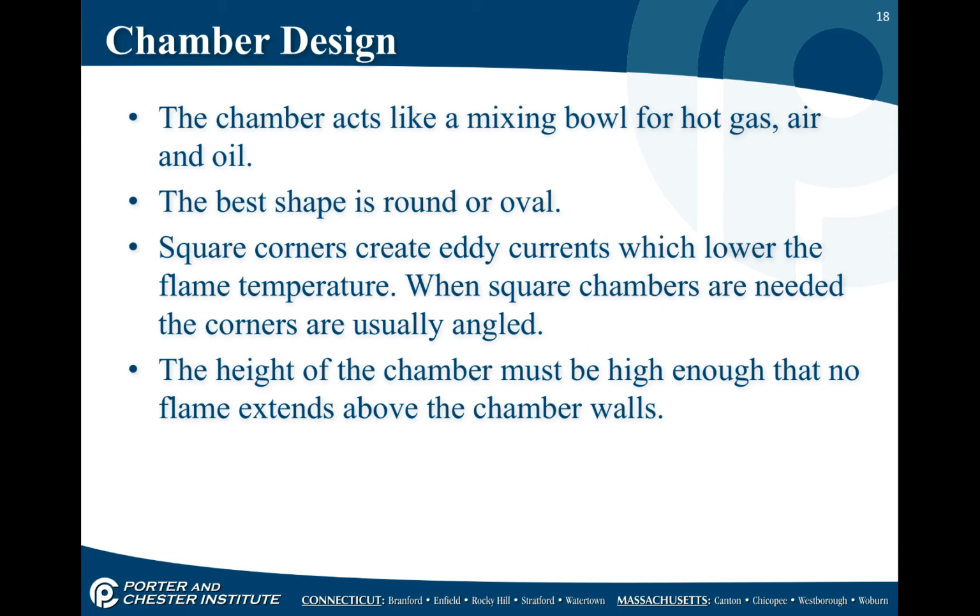The best shape for it is round or oval. We don't want to keep square corners because then we have eddy currents, and that's a pretty important term for those of you getting licensing because it does appear on state tests. We create eddy currents which lower the flame temperature. An eddy current is when air blows out of the burner tube and hits a square corner, it creates an air pattern that actually disrupts the combustion process.